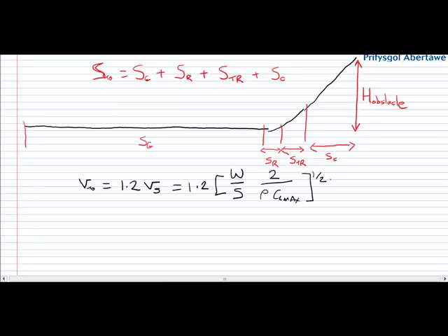That should have been done a long time ago. The air density, and obviously that's driven by the altitude of the airport, or the strip, in your case the dirt strip that you're going to be taking off from, and your current estimate for your aircraft's maximum lift coefficient.